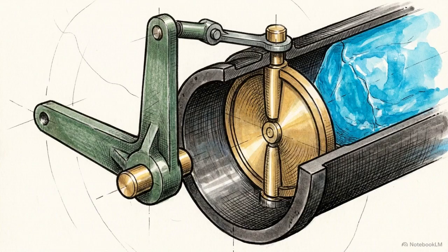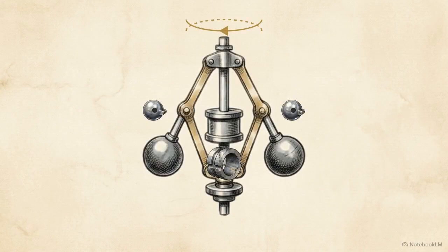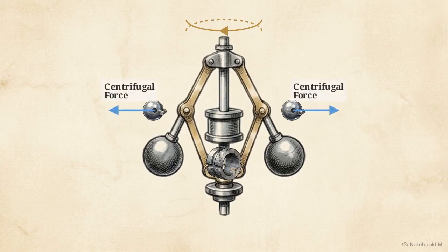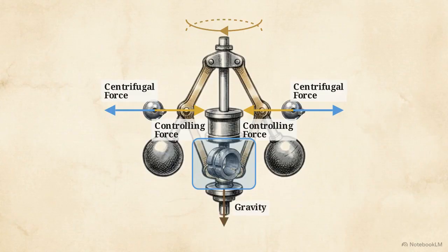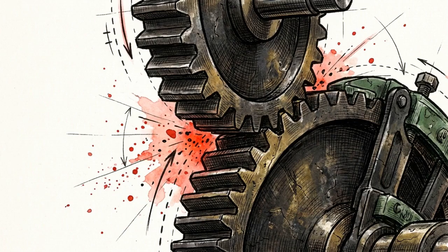allowed to power it. Under steady-state conditions, the outward centrifugal force on the flyballs is balanced by an inward radial force. This inward controlling force is provided by gravity acting on the mass of the sleeve and the balls, pulling the mechanism downward and inward. If a sudden increase in external load is applied to the engine, the equilibrium shifts.